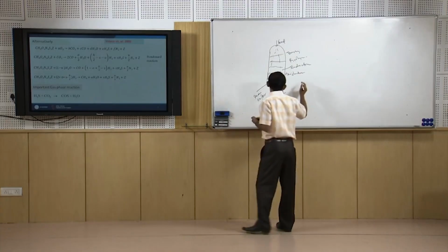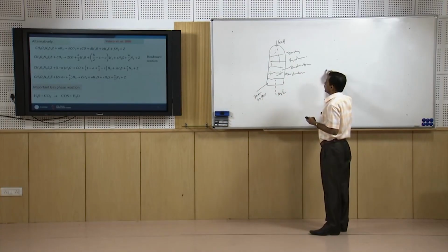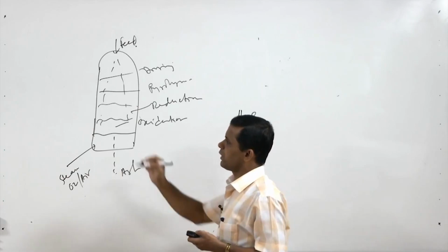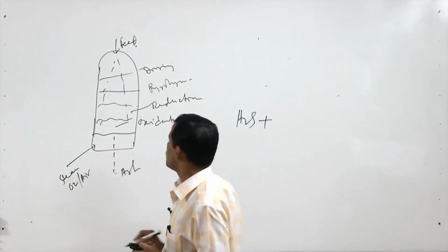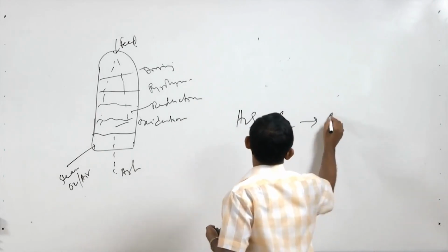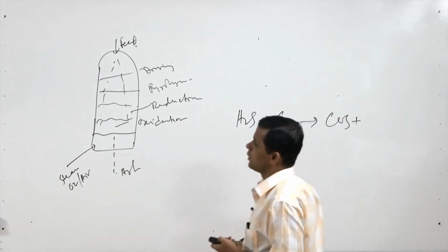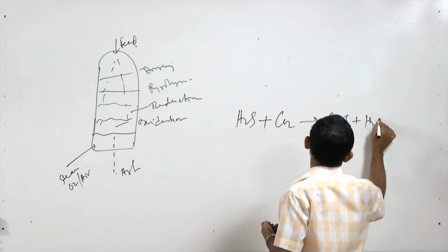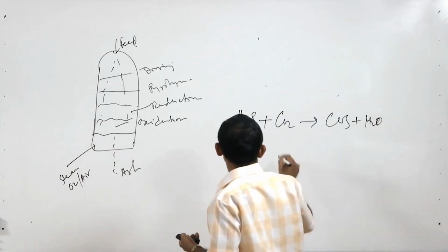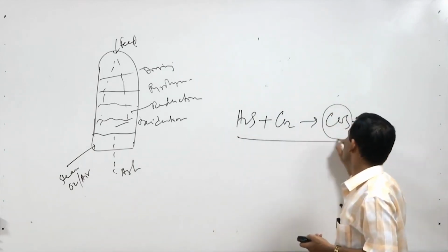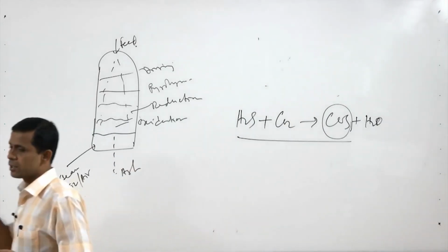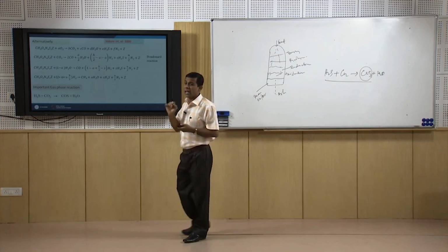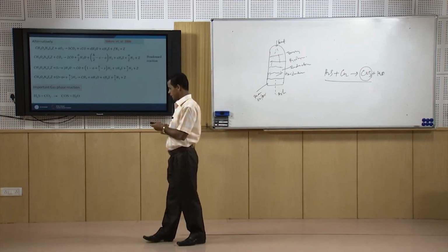It is also proposed that the H2S produced in the basic reactions reacts with CO2 and converts to COS plus H2O. This is how COS is present in syngas, which needs to be cleaned because those components are not desirable and we have to remove them.